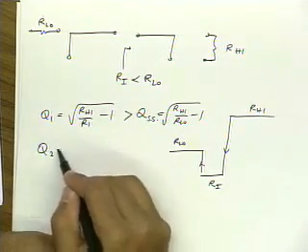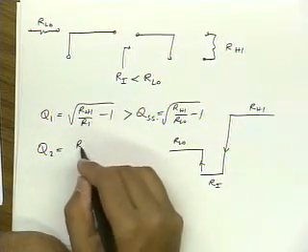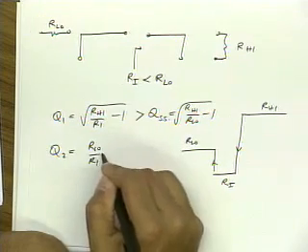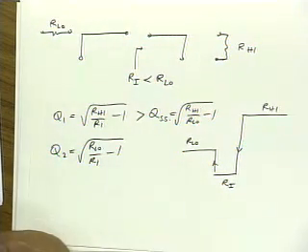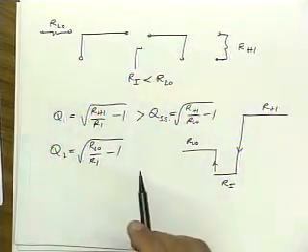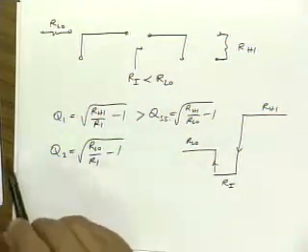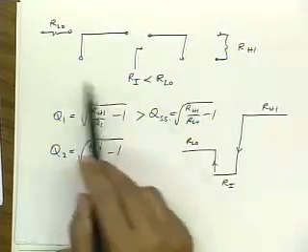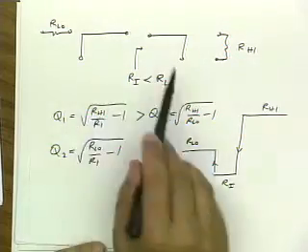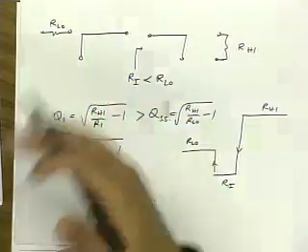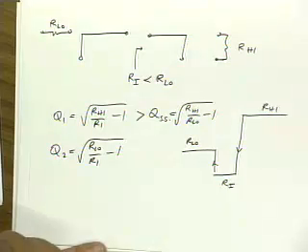And Q2 is perhaps even higher as well. It'll turn out, and we'll show this later in the lecture, maybe next lecture, that the quality factor of this overall matching network is the average of these quality factors. So I've raised the average quality factor, so this is going to be a higher Q circuit. So it's the opposite of the previous case.